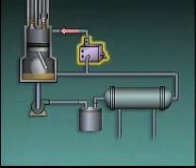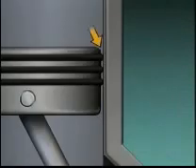The oiler supplies a small amount of oil to the compressor cylinder. In the cylinder, piston rings are used to maintain a seal between the piston and the cylinder. The oil lubricates the piston rings and helps seal the space between the cylinder wall and the rings. Compressed gas systems use auxiliary devices to remove oil or moisture from compressed gas and to prevent overpressurization. Two devices that are used to remove liquids from compressed gas are oil separators and demisters.